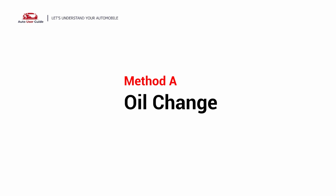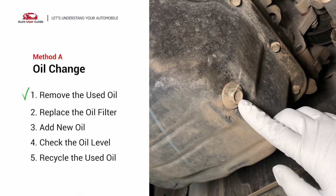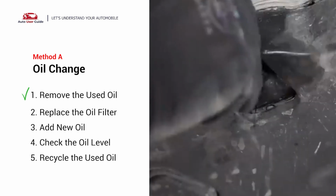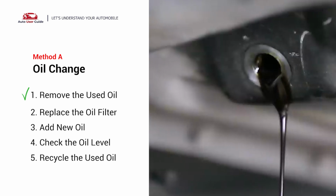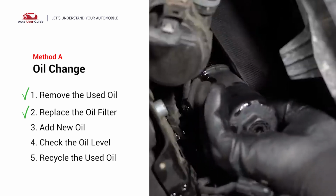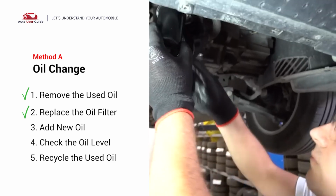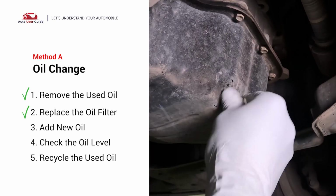Method A, oil change. Locate the oil drain plug on your vehicle and place an oil collection pan underneath it. Loosen the nut. Drain the engine oil. When the flow of the oil gets slower, use the oil filter wrench to loosen the oil filter. Apply some seal on the new oil filter. Now tighten the filter in its place. Then retighten the nut.